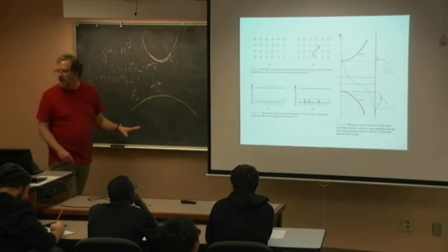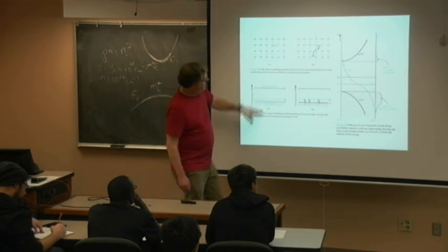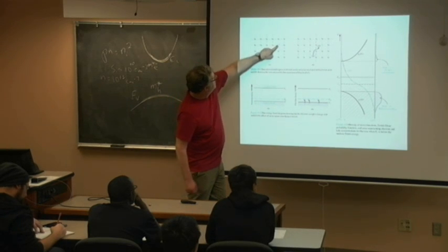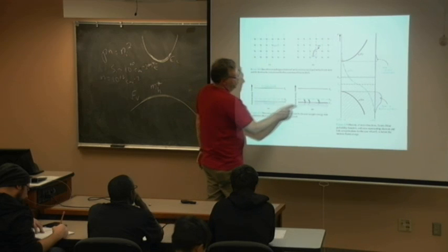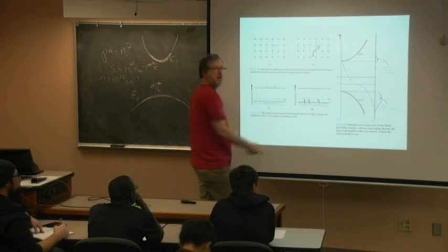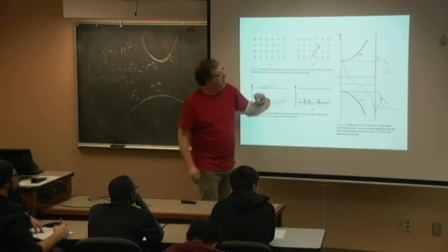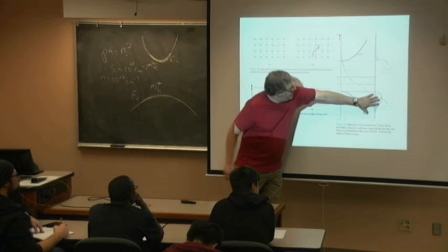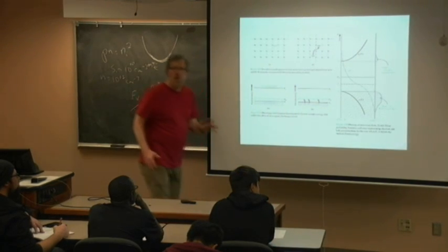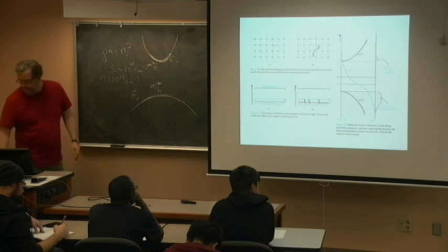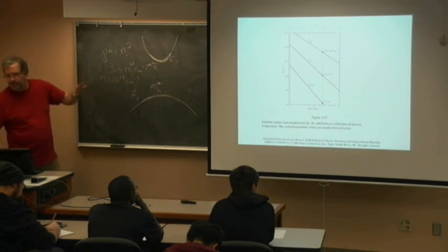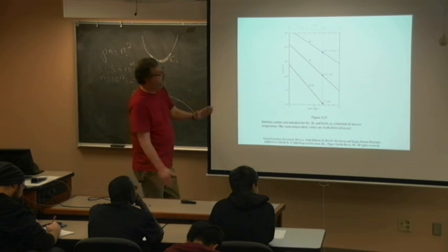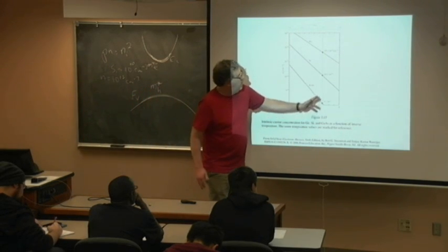And this ties together the boron, the opposite. It's putting in the energy level there by the boron substitution. It's missing an electron, so it steals an electron from the valence band, thereby creating the free hole. And so it creates this rich area of holes, so it's p-type. Here's the whole thing together, and so we end up with that intrinsic carrier concentration, ni.